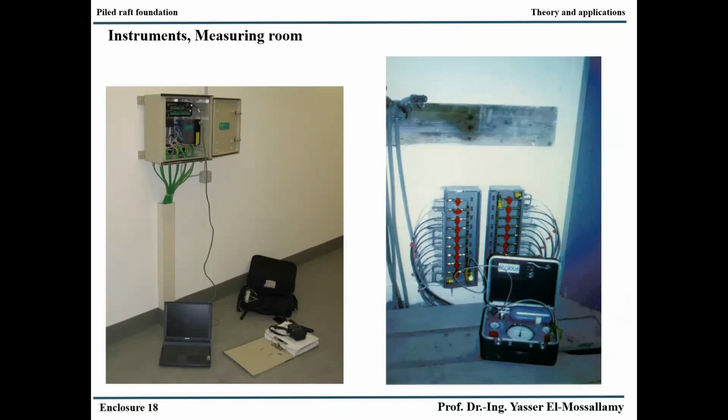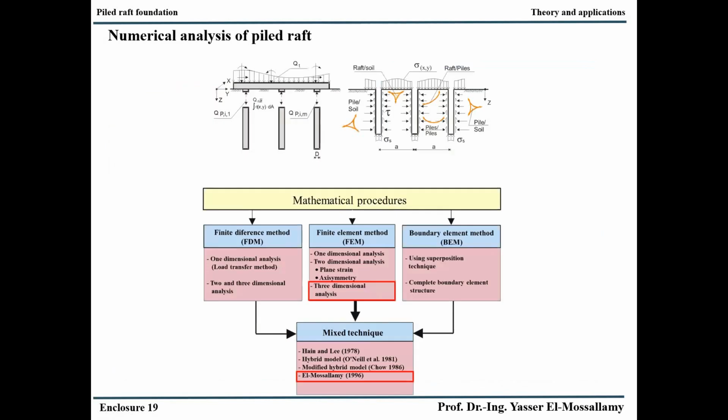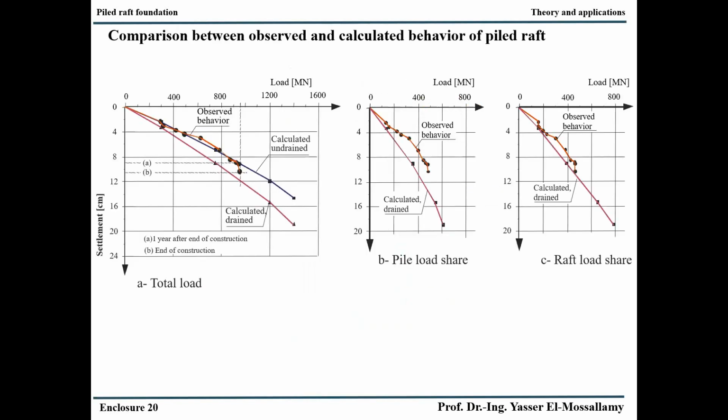Nowadays, we can have a modem system here with a digital system, and then the measurements can be sent automatically over the internet to your mobile or to your office, and then you can see online measurements for important projects. Now we go to the numerical analysis of raft foundations, and in numerical analysis we have a lot of possibilities, but to keep this short we will only use the three-dimensional finite element analysis.